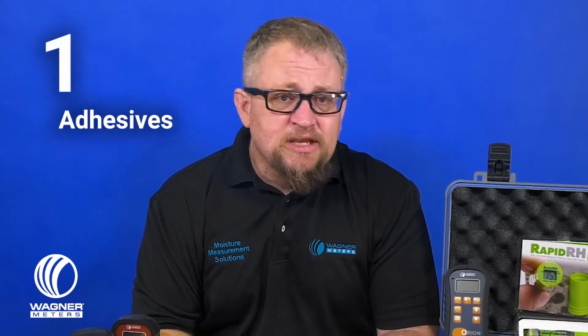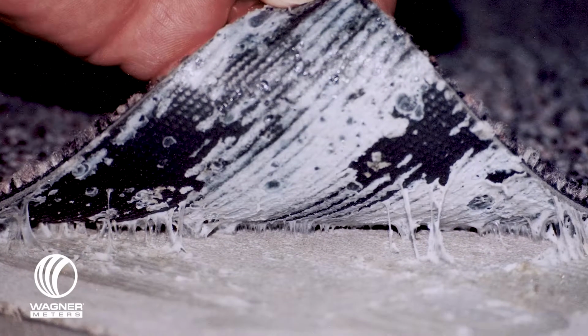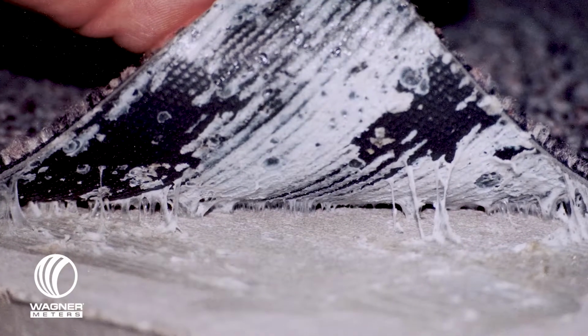First, a few flooring products that may be susceptible to moisture-related problems: adhesives, floating floors, and grout or cementitious bonds. And what's the likelihood you've installed products of this nature? So number one, adhesives. Thanks to restrictions on flooring adhesives regarding volatile organic compounds or VOCs, more moisture-sensitive adhesives are being used. But if the adhesive does not have the correct moisture or pH tolerance, the entire installation can be at risk.